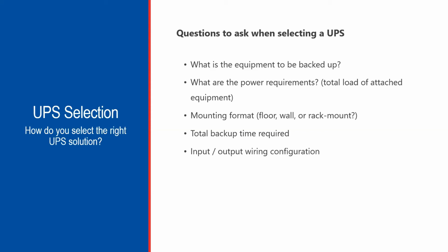What mounting format is needed? Believe it or not, sometimes people do overlook this particular question. Maybe they don't need a rack tower. Maybe they just need a simple tower unit. Maybe they don't have availability in their current rack situation. So understanding what mounting format you need is necessary. But all UPSs are available in a multitude of configurations, which will prevent any sort of installation issues. Understanding the format will help you pick the right UPS.